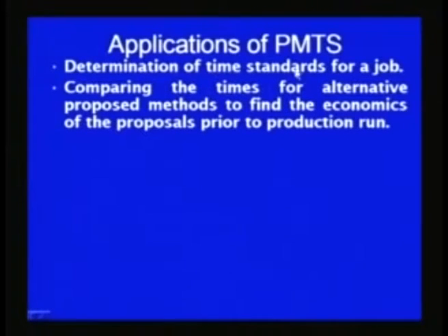The time standard can be set by identifying the different motions which are required for carrying out the job, and summing up the time required for performing each motion helps to come up with the time required for doing a particular job. It also helps to compare the time required for carrying out a given job through the different alternative methods which are being proposed.